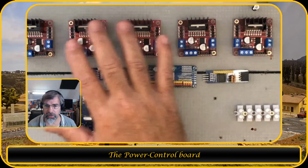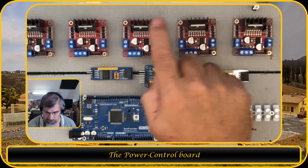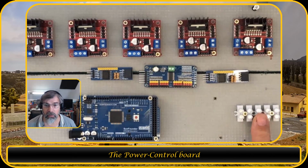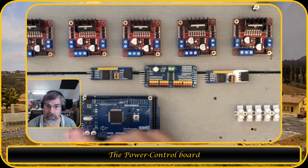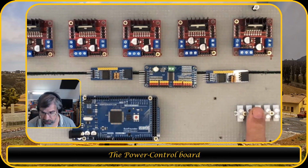So this is half of the power section of the main track. These are the motor drivers which control the power on the track. This is a terminal block where the 5 volt, 12 volt and ground come in. We have here the Arduino. This one is going to control all the power sections. I have here a barrel connector which is going to be connected to this same terminal block.